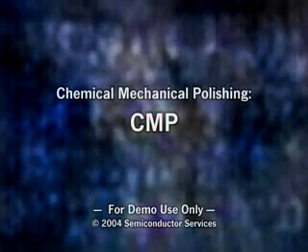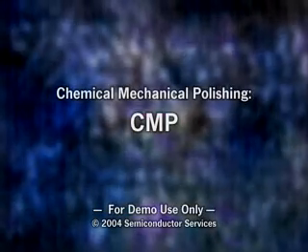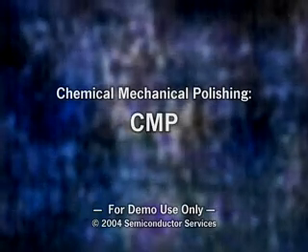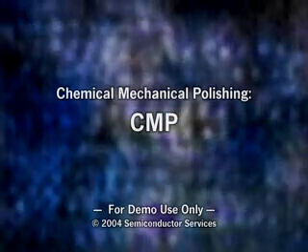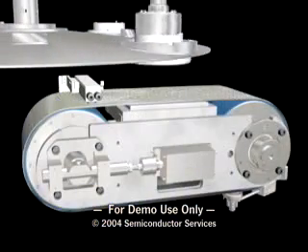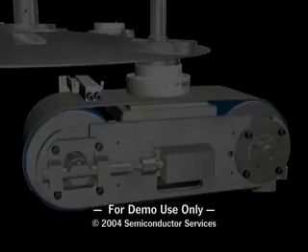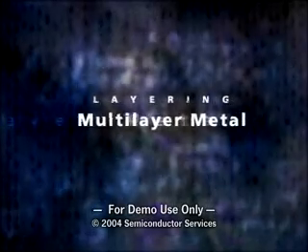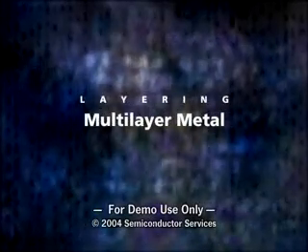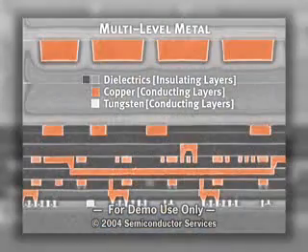However, the most important planarizing technique is chemical mechanical polishing, or CMP. CMP combines chemical action with light mechanical polishing. Metal layers, deposited and patterned on the wafer surface, are used to connect the individual components, creating an integrated circuit.